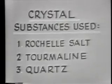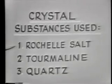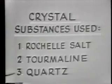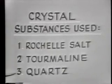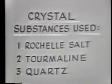Of these three, Rochelle salt exhibits the piezoelectric effect to the greatest degree. However, quartz crystal is most generally used because it has a greater mechanical strength. At this time, let's complete the B part of item 2. The substance most often used in oscillators is, go ahead and complete that blank. It is quartz crystal. Remember, it has a greater mechanical strength.